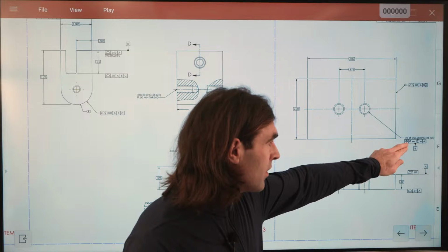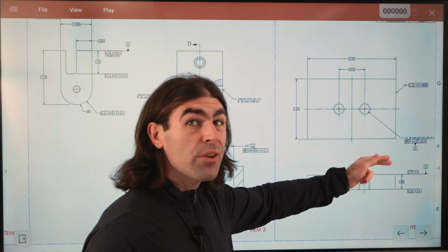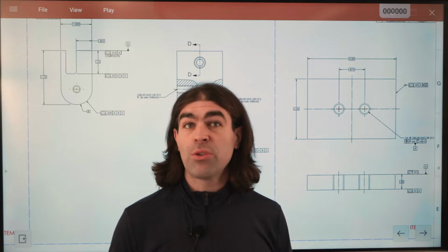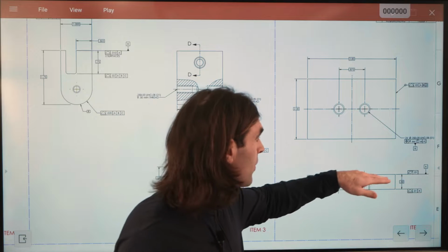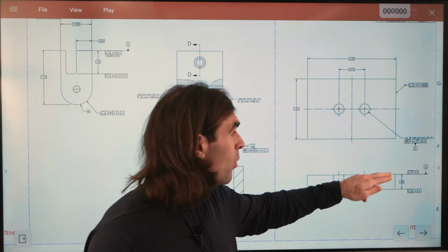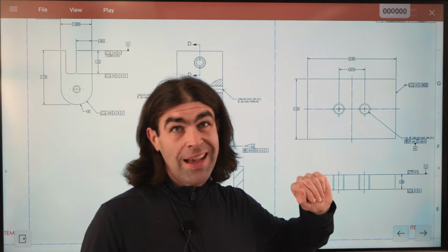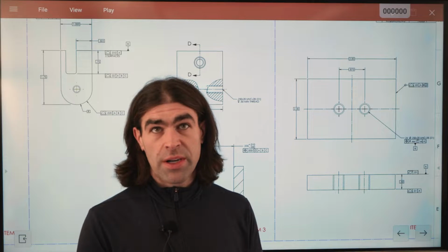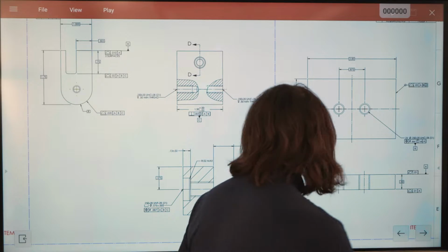We're going to have a position tolerance, which we're going to calculate in a minute for those two holes. And then we've got our datum feature symbol indicating that those two holes make the pattern. So the size of the holes is 1/4. There are two threaded holes. We'll have a projected tolerance, and I'll show you how to calculate that as well, so that we don't have to calculate the tilt when it goes through the next part.